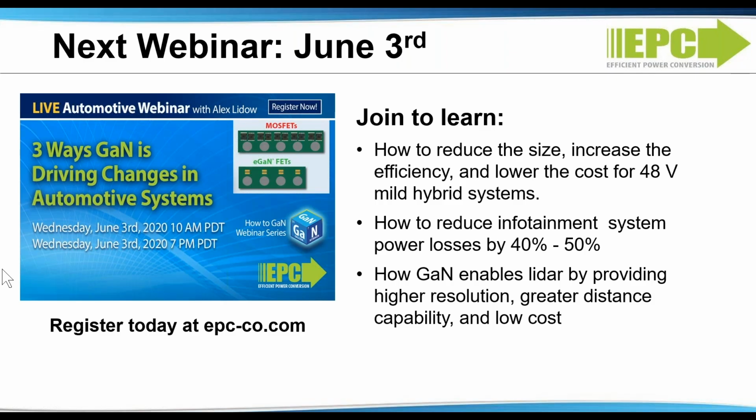The parasitic inductances cause overshoot and ringing. That is the primary energy source for EMI and EMC. So by reducing overshoot and ringing, if you reduce it by 1/2, I believe the EMI goes down by 1/4. It's the square of that.